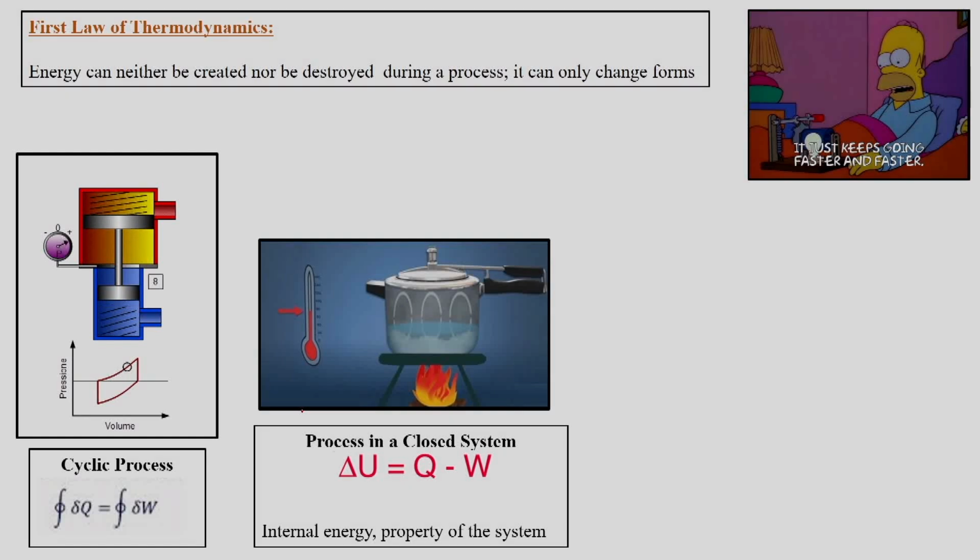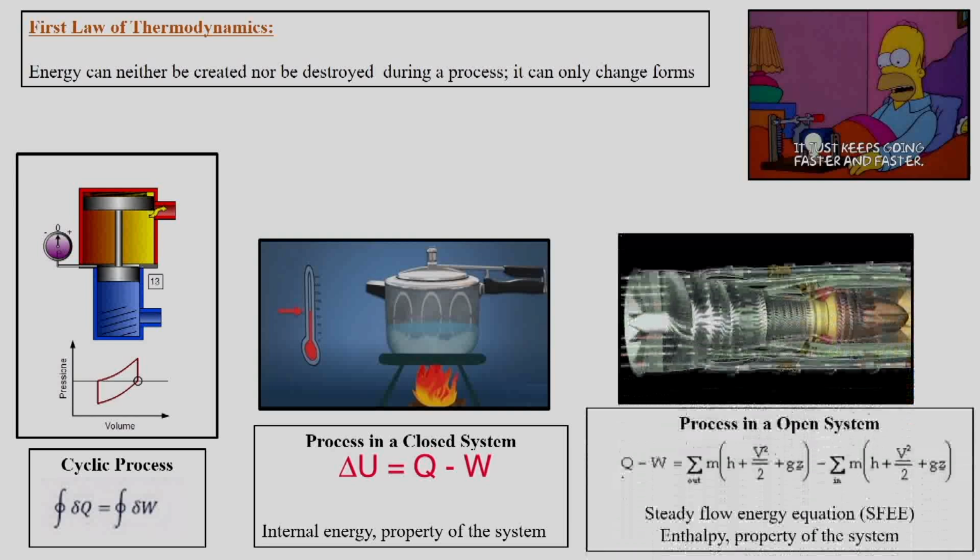then if we take a particular example of a cooker, where we are supplying heat to a pressure cooker, there will be, suppose, water or food inside the cooker, and it would change its internal energy by virtue of the heat addition. In this particular case, we would not have any work interaction, but in a closed system there is a possibility that there will be work interaction by motion of the system boundaries, though this is a closed system with fixed boundary.